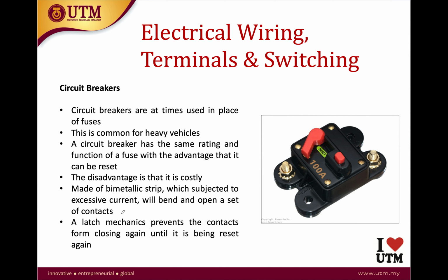Aside from using fuses, you can have circuit breakers. Usually this is meant for heavy vehicles or commercial vehicles. A circuit breaker has the same rating and function as a fuse, but the advantage is that you can reset it, so you don't need to replace it, and it will not be damaged so easily. But this comes at a higher price. It is usually made from a bimetallic strip. The latch mechanism will prevent the contacts from closing again until it is reset.